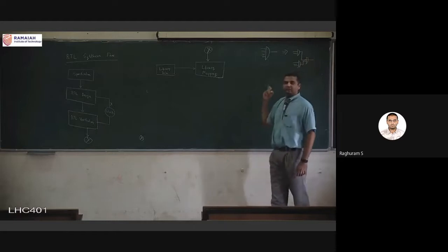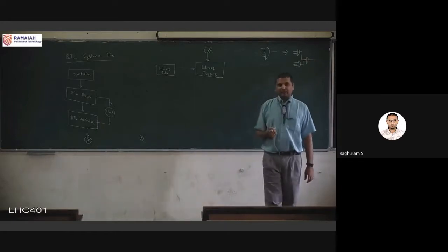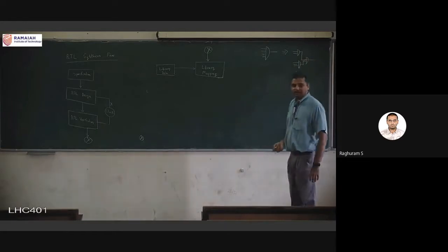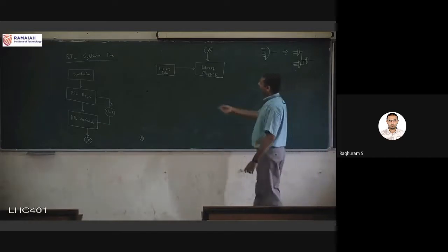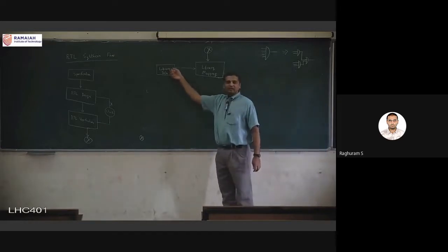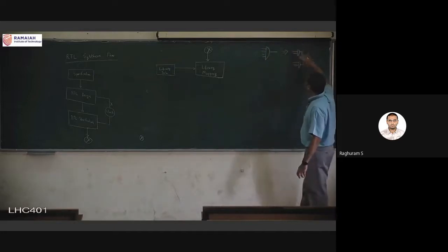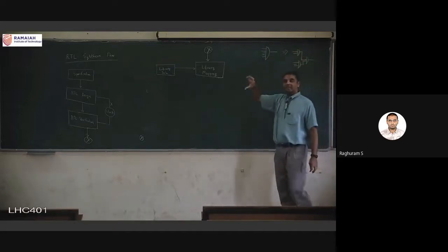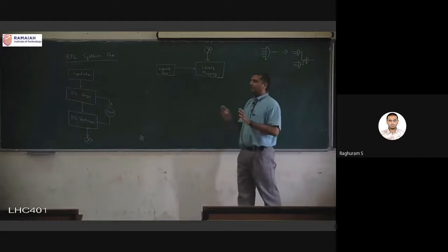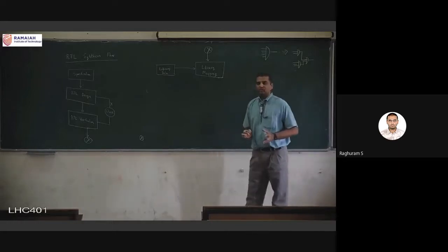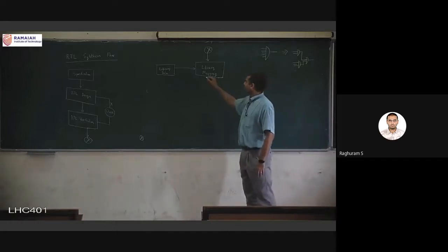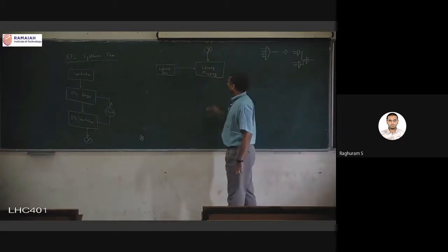2 input and 3 input are there in my library. So instead of one 5 input AND function, I will see in my library what other gates are there, okay, and try to transform the 5 input into available gates. That is the mapping, and again, completely based on software tools. We cannot do this without the software tools, but this is very important because at the end of this step, okay, we have